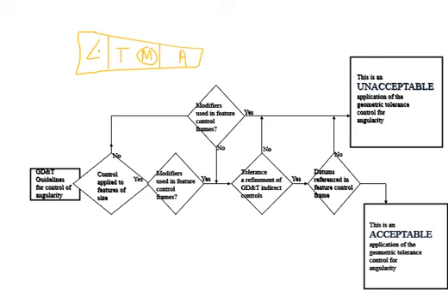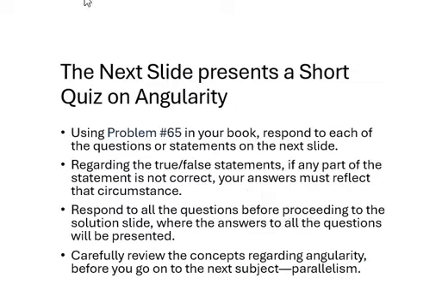Okay, so for angularity, you look at whether we're dealing with the feature or feature of size, just size or the feature. Then you look at the modifier. This can also be L. And then after that you look at the tolerance, and sometimes you also have another tolerance right there. And then your datum. So that's what we're looking at.